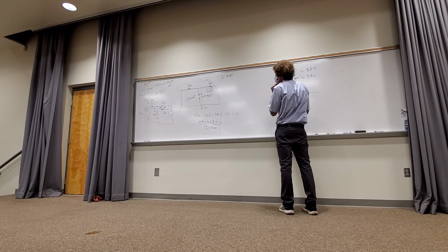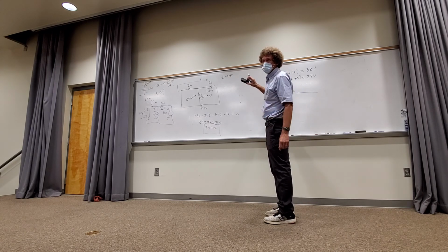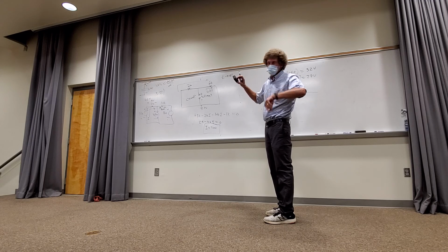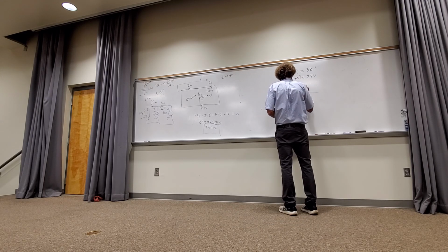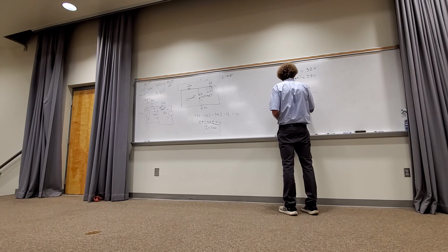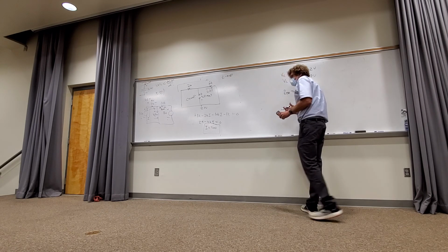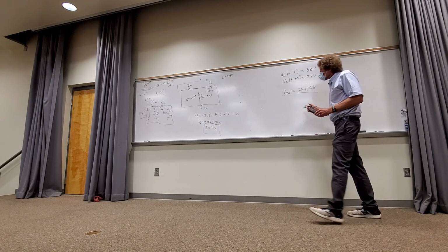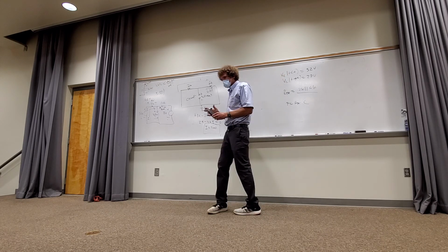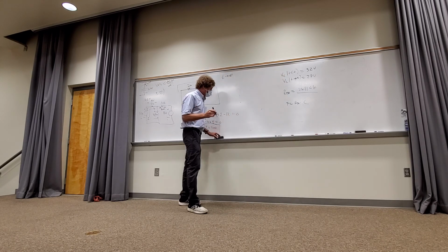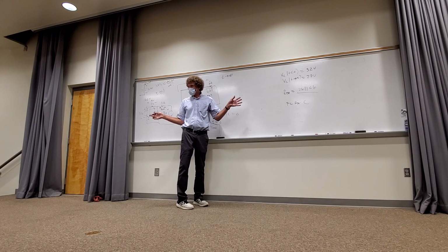I have, this is going to be what? I'm just going to leave it as 2K in parallel with 6K so everybody can see what I'm doing. All right? That's it. And that means tau is what? R Thevenin times C. Just let me finish here. All right? Now, I'm about out of time, but y'all follow me what I'm getting. I'm going to get R Thevenin, then I'm going to get tau.